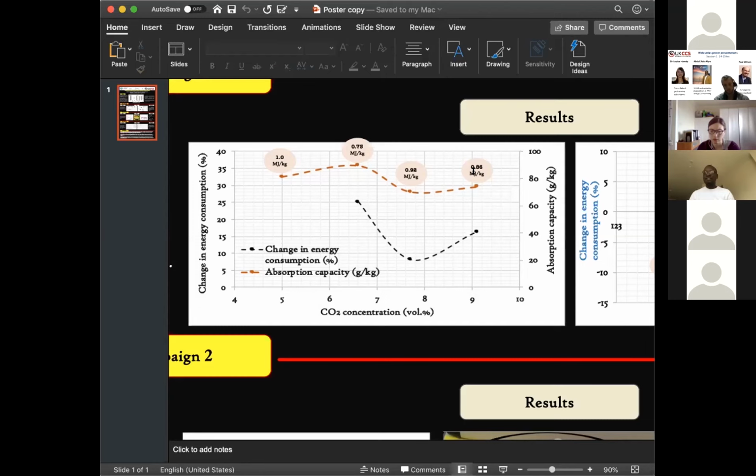Third, with selective exhaust gas recirculation, the pH value of your solvent decreases. And under that circumstance, it's liable to increase the corrosion of the internal equipment of your plant. The corroded ions in your plant are liable to corrupt your solvent, which increases your operational expenditure, and also increases the capital expenditure due to the nature of the corrosion because of the lower pH value.